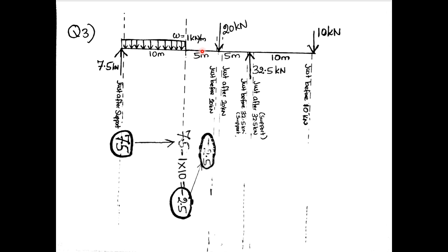There's no force, therefore here minus 2.5. There's no force up to this point, minus 2.5. Here minus 2.5. Again minus 20, because downward. At this point, shear force is minus 22.5. Again this one minus 22.5. There are no loads, therefore here also minus 22.5.